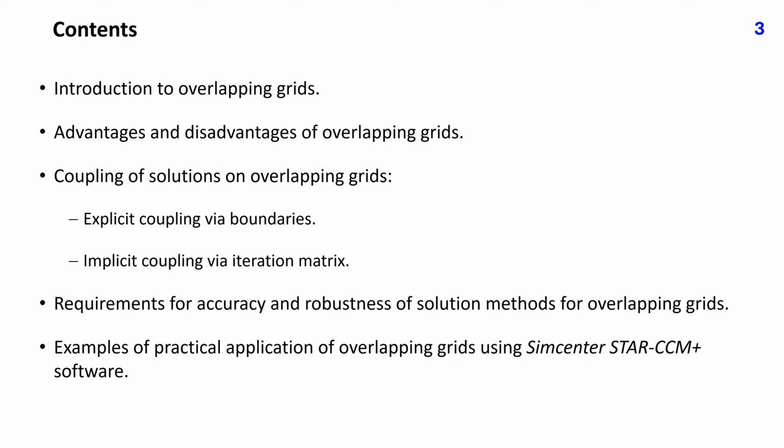Finally, Simcenter STAR-CCM+ software is used to highlight the features of solution methods for overlapping grids on three examples. In one, automation of parametric studies like different angles of attack in simulation of flow around bodies is shown. The other example is the mixer studied in lecture 26 using a sliding grid interface. Here, the two approaches are compared. Finally, in the third example, a mixer with two impellers is used to highlight the ability of overlapping grids to handle moving parts with intersecting paths where the sliding grid approach is not possible.